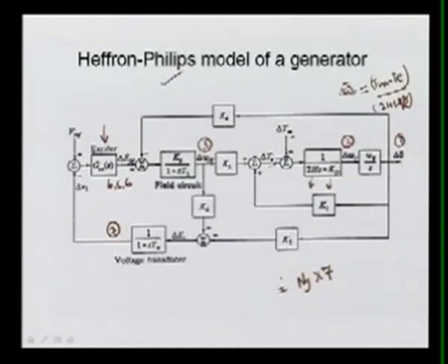Now in this case we have not considered the power system stabilizer. If you are going to use power system stabilizer, you have to use here one auxiliary system, and that is VSS, that will be added here. So again, if you are going to include that, then the states of your power system stabilizers are also going to be added, and the total number of states will be increased accordingly. So this is your exciter.